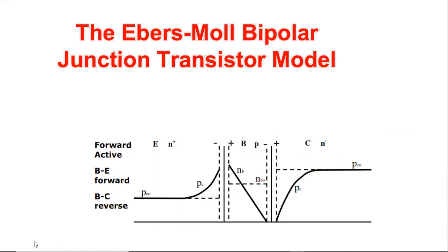So if you remember from the PN junction, we say when a junction is forward biased, then we have a huge number of holes coming from the P side to the N side. That's why the minority carriers increase, and that's why you have this curve like that. We name this region delta p, which is the excess minority carrier, and this p_n0 is the steady state or thermodynamic equilibrium value. So this increase represents that this junction is forward.